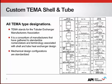It is also more suitable for higher pressures, typically due to the use of an elliptical head cover, where a rounded cover is better suited for higher pressures as compared to a flat and bolted cover. A Type N is a non-removable channel, but similar to the A with a removable cover. It also has a non-removable bundle. So this can be a less expensive option depending on the pressures, temperatures, and metallurgies required.